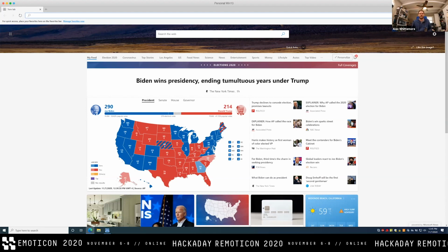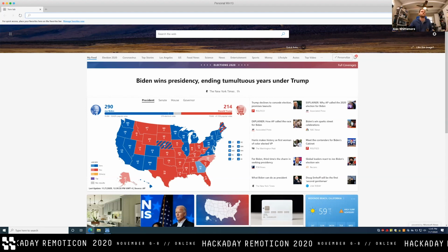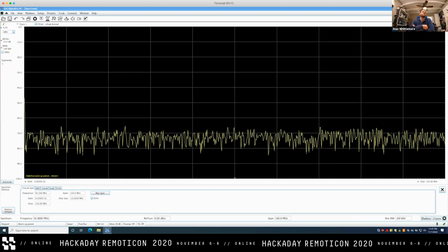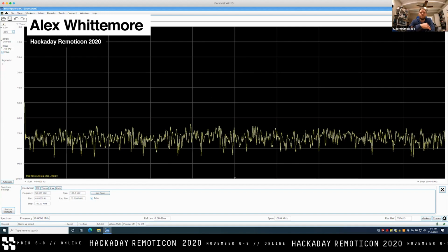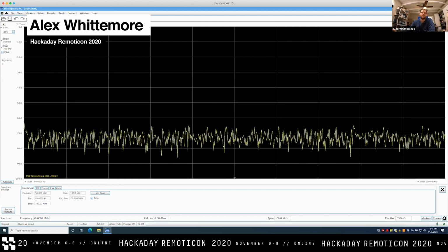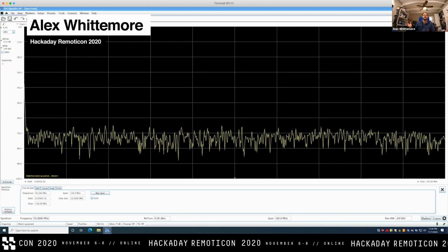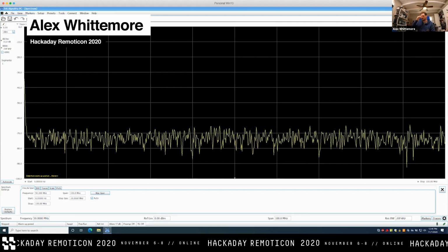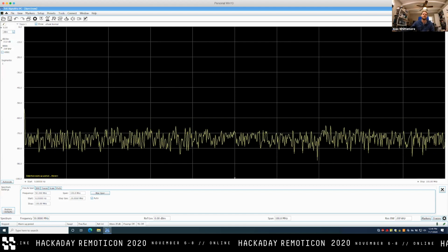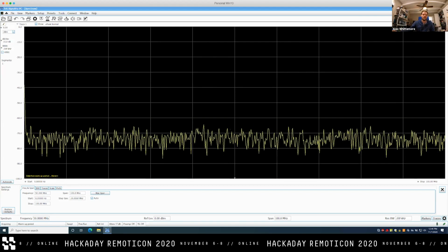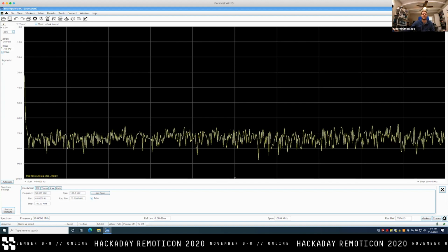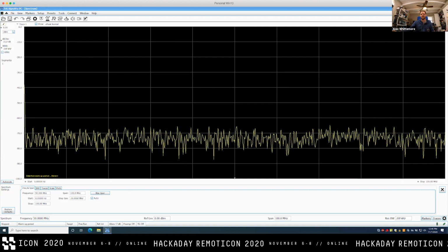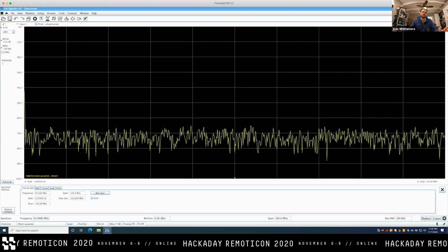If you've got multiple devices operating on that same circuit and you need to time synchronize them, it blasts a 60 megahertz clock out on one of those pins. So that's probably what we're spotting there. And now you just go look at the pinout for the device and see, is that what I'm seeing? Is that signal that I know exists in another part of the chip coupling on to that signal that I was measuring erroneously, or what's going on here?